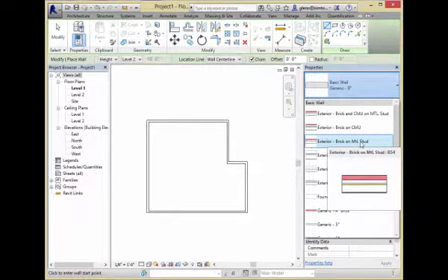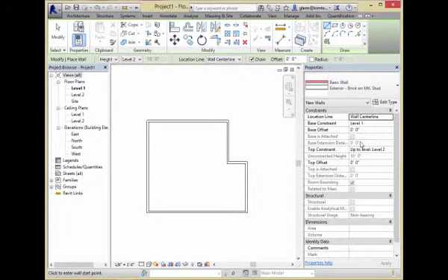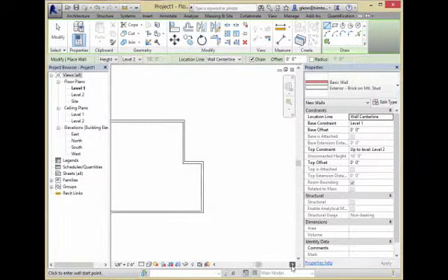You can see it has a bunch of different layers in there. That's got some core layers, a sheathing layer, some air, and some brick. There's some different layers in there. And as I go drawing those, now this is going to get to be more critical about this notion of, am I centering it? Am I putting it on the inside or the outside face? And let me show you what I mean. I'll start by placing the wall just on the wall center line.